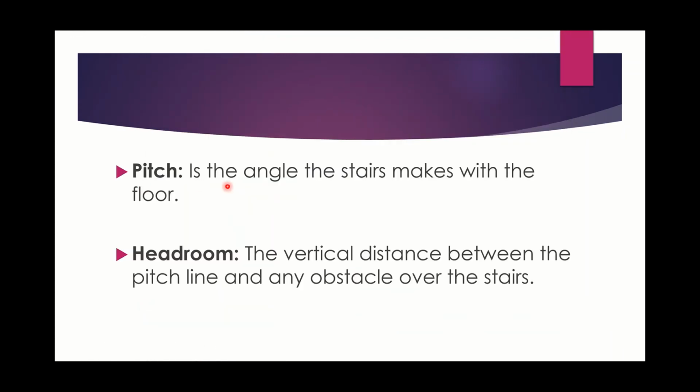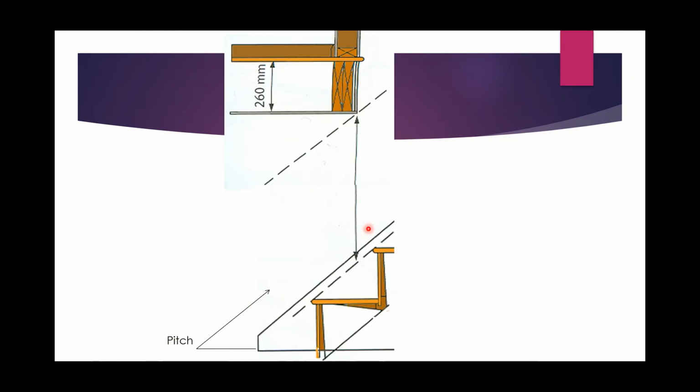Pitch, this is the angle the stairs make with the floor. And the headroom is the vertical distance between the pitch line and any obstacle over the stairs. So your pitch is the angle of the stairs. 35 degrees is the optimum or the perfect angle for a set of stairs. That can vary obviously. And your headroom refers to this distance here.